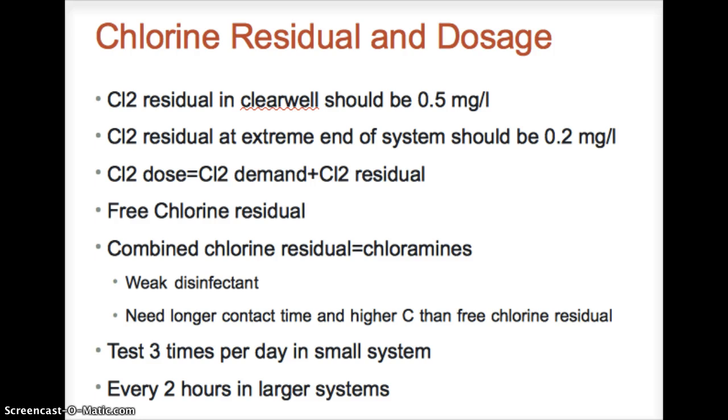And again, a reminder that chlorine dose equals demand plus residual. And that residual is called free chlorine residual. And the combined chlorine residual is the same thing as chloramines. They are a weaker disinfectant, they need longer contact time, and they have higher chlorine than free residual chlorine. Forgive me, I think that might be a typo. Anyway, it's fine. They do need longer chlorine contact time.